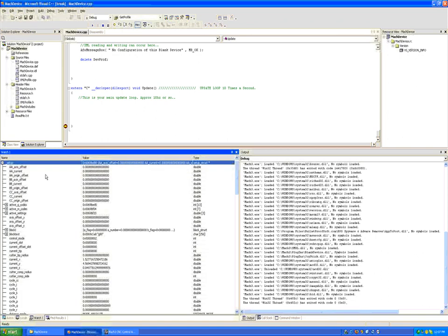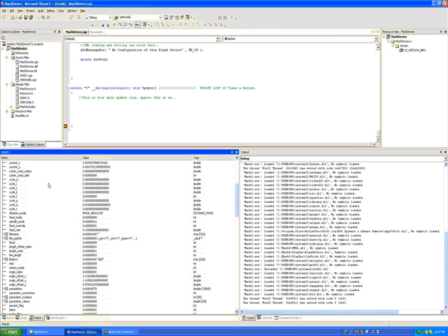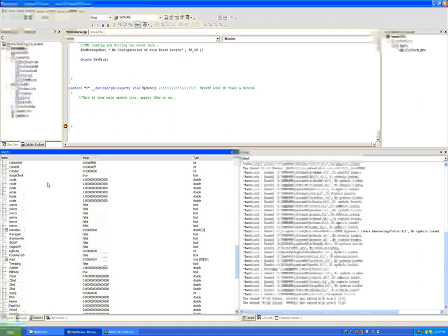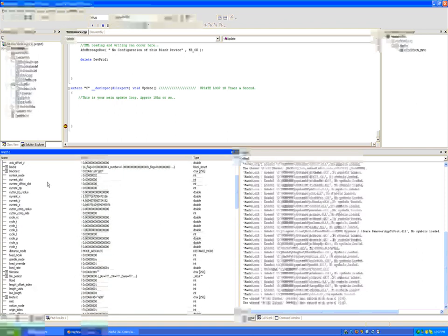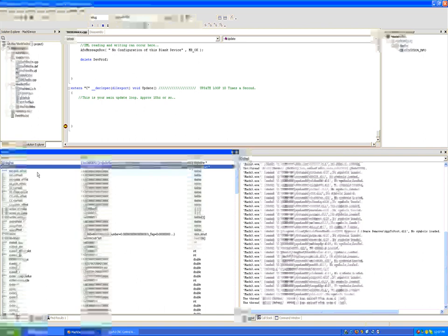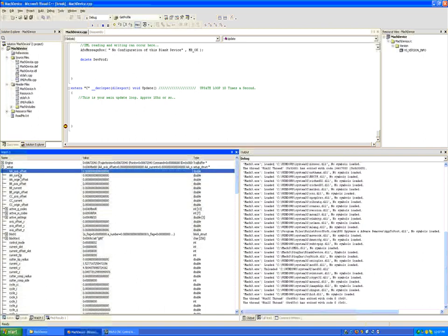Setup block, if I open it up, you can see that it really reflects all the states of the trajectory planner. I realize this is hard to read, and again, you're going to want to do this yourself, but you could see, for example, here's our current work offset, or AA axis offset for the A axis. My apologies, that's the G92 offset.